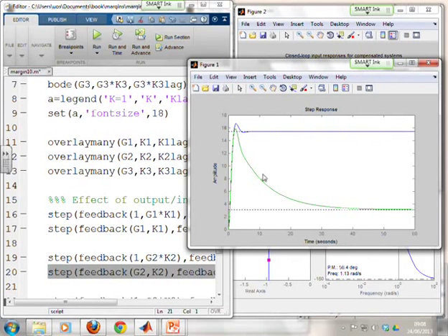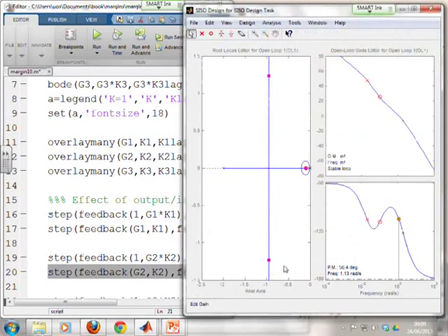You notice for an input disturbance, the lag compensator has a significantly smaller offset than the simple gain design, obviously by a factor of 5, because that's the beta that we used. So the real benefit of the gain recovery for systems with integrators comes when you're rejecting input disturbances. Of course, it will also reduce offset to ramps, but ramps are a fairly rare thing to have to deal with. Right, let's look at the final example now, and see if we get the same messages.